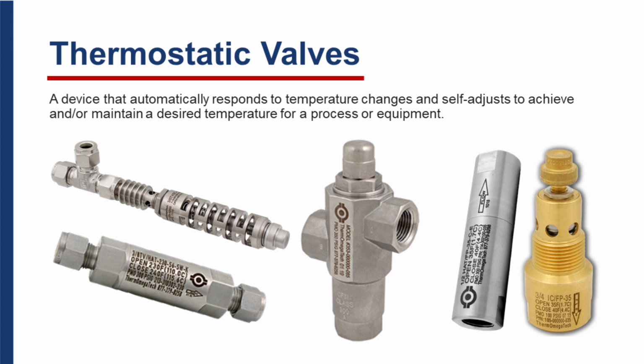It's a device that automatically responds to temperature changes and self-adjusts to achieve and/or maintain a desired temperature for a process or equipment. You see the two valves on the left-hand side. Those are basically two-way valves in that they have one inlet and one outlet. In this particular application, they're used to keep an enclosure at a certain temperature or to keep a certain line within a certain temperature.